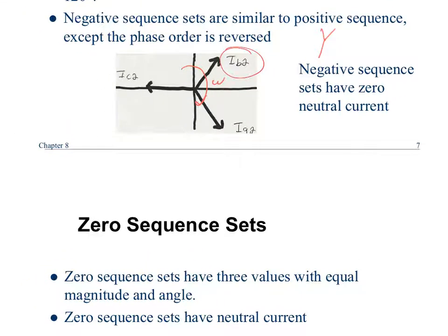that guy: what is the negative sequence current? If we're assuming ABC, positive sequence rotation, that value can be whatever it needs to be because it's based on load. If you have any negative sequence current, that tells you the system's unbalanced. And some systems you expect to be unbalanced, like distribution circuits.